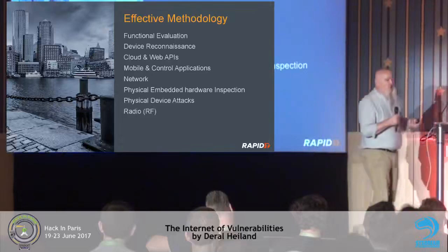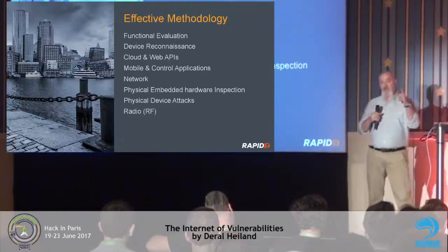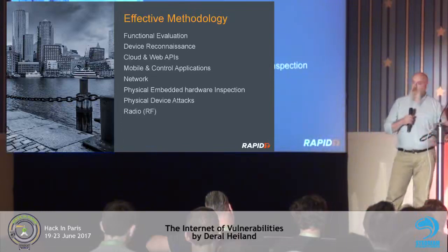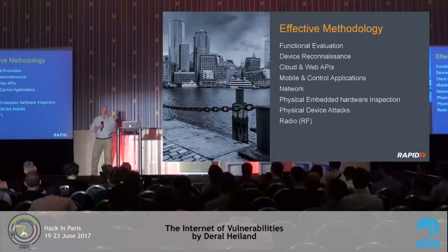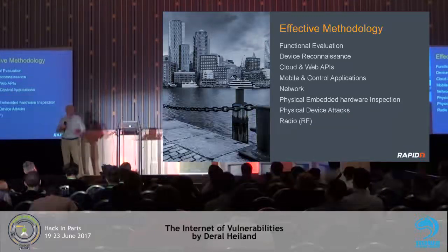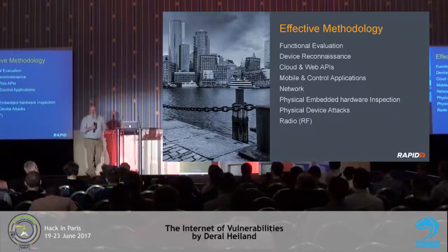And then we go off and we focus on all the subcomponents that I mentioned of that ecosystem. We look at the cloud and web APIs. We look at the mobile applications, the control applications. We look at the network. We look at the physical embedded hardware. We break it down and look at it. What is it made up of? What are all the pieces? Does it have USBs? If I open it up, can I find landing points where I can hook up JTAGs, UARTs? So we map out the entire piece of the hardware, and then we do physical attacks on the device.